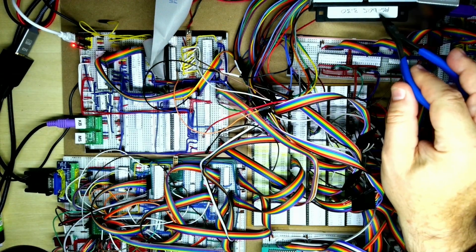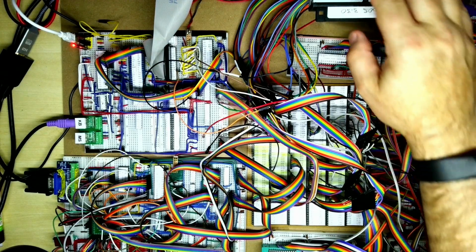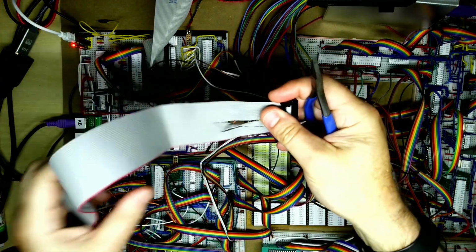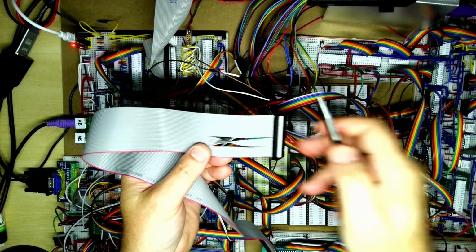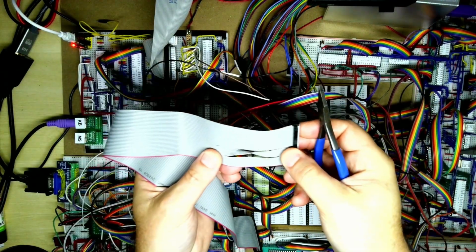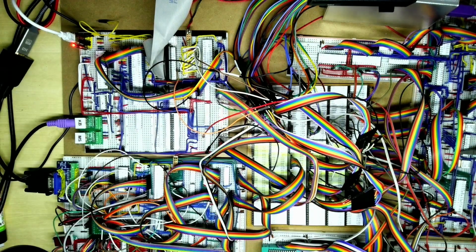I have tested that the disk and the floppy disk drive all work in an old Compaq Deskpro PC I've got access to. So I know that that is working, and it's using one of these crossed floppy disk cables. So most relatively modern floppy disks come with drive B configured, and this twist is necessary to turn it into drive A. So that's why these cables look like they do.